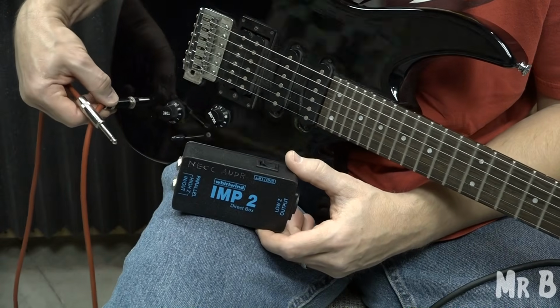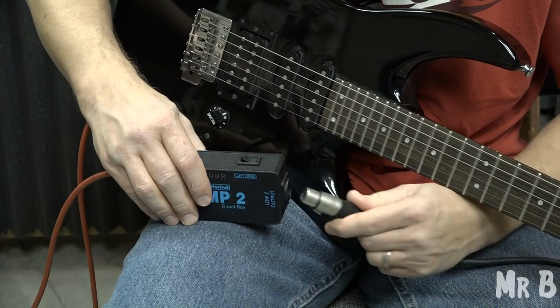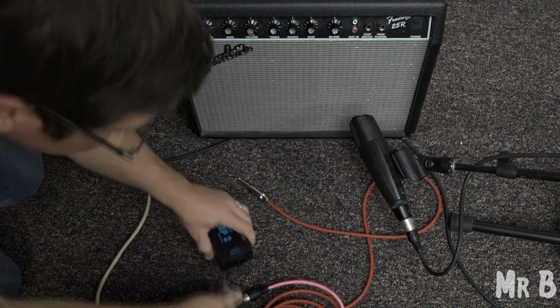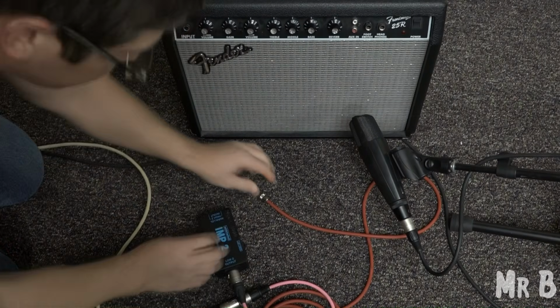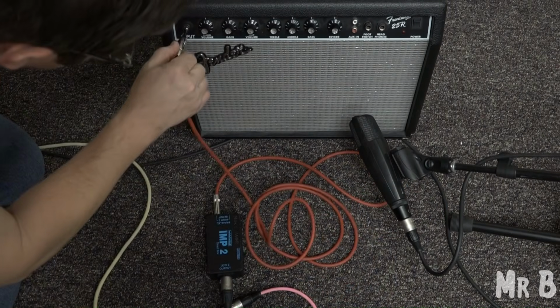Next, set yourself up in the room in which you'll be playing. Plug your guitar or the output of your pedal board into the first DI box. This steps the signal down and converts our output to low impedance. Now run the mic cable into the room where you have your amp. Use the turnaround to plug the mic cable into the second DI. This steps the signal back up to high impedance. Then plug the 1/4" connection from the DI into the amp.